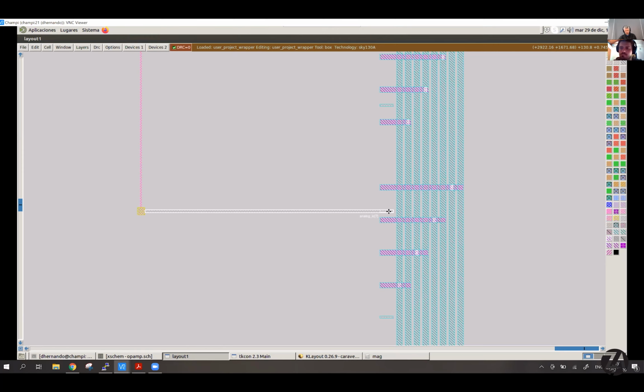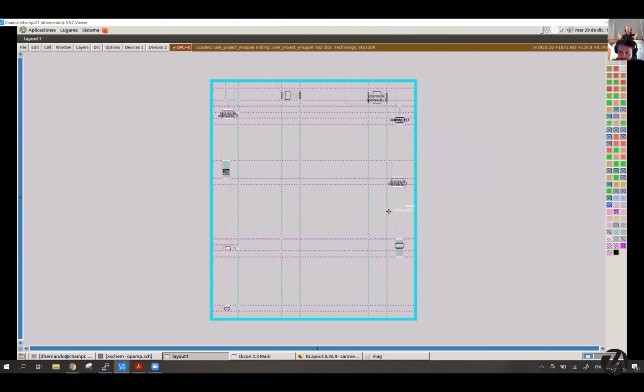Here's another question that's maybe about the difference between the digital and the analog. All my designs, they're not going to do anything until the RISC-V chip, Pico RV32, boots up, loads its firmware, runs a program that sets the IOs correctly, and then my design should run. Will your design just run without any external flash because there's no configuration needed? In the case of the opamps, yes.